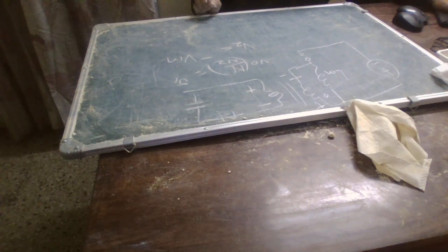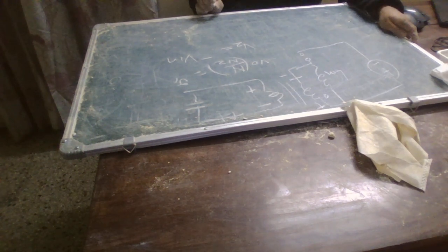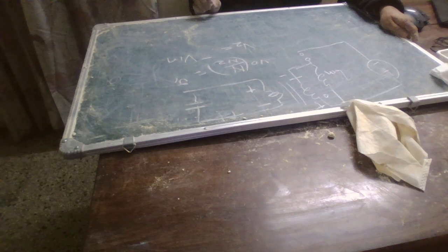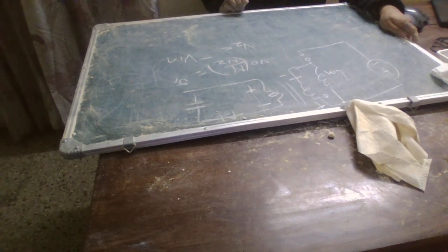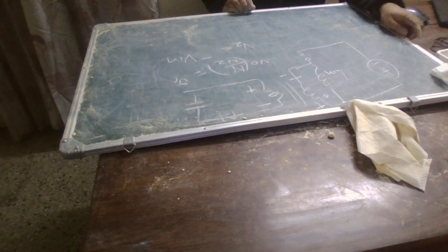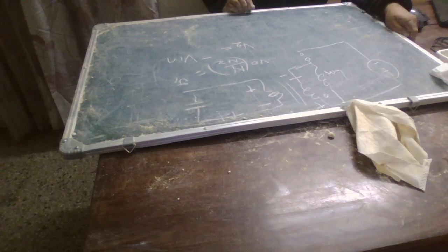So this is the mathematical operation during the switch open time. Because the current cannot change instantaneously in this magnetizing inductance, there has to be some conduction path or current path, as I talked about in the beginning. The snubber is going to be used for that. This ILM enters the undotted terminal of the primary, and it must exit the undotted terminal of the secondary.